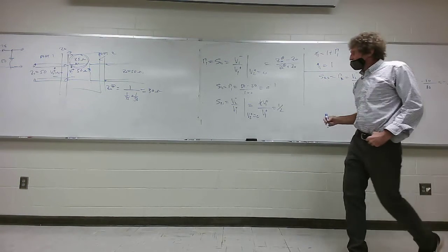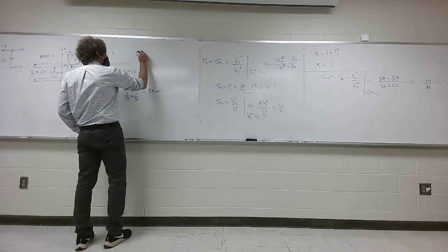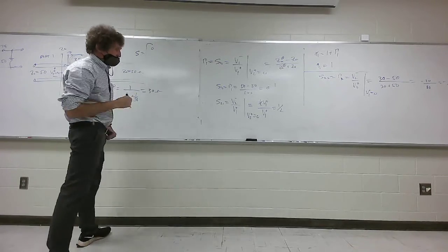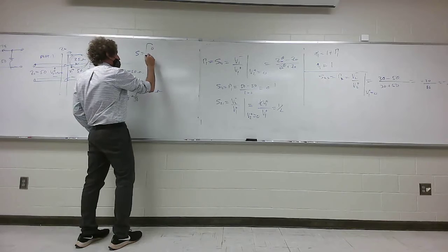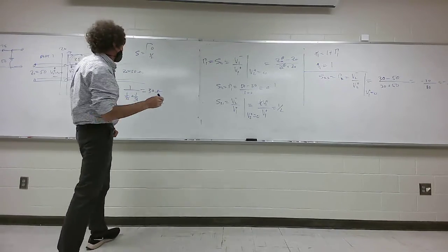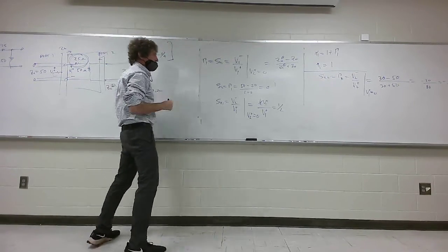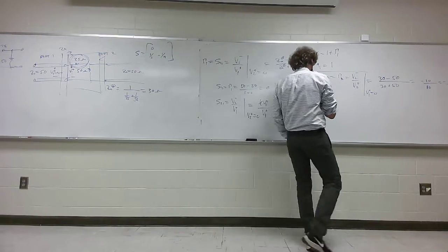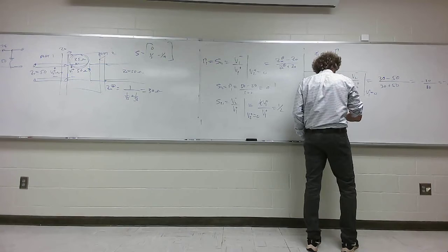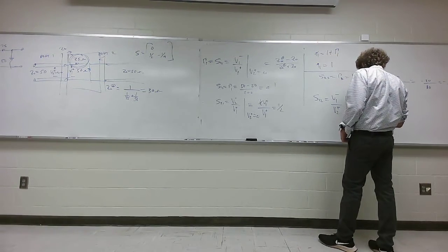All right, so here, I know that if I'm starting to make my S parameter matrix for this, S11 is 0, right? S21 is 1/2. S22 is minus 1/4. Now we need this guy. We need S12, which is V1 minus over V2 plus, assuming V1 plus is 0.